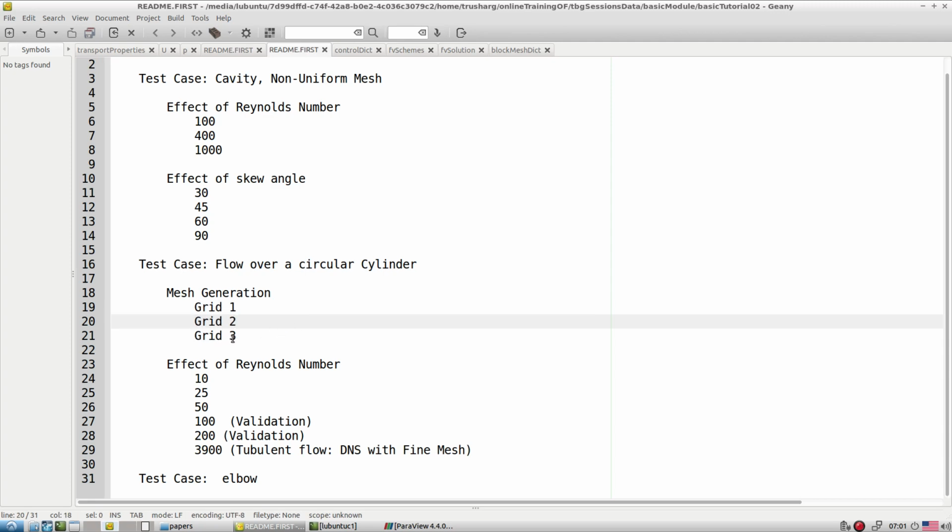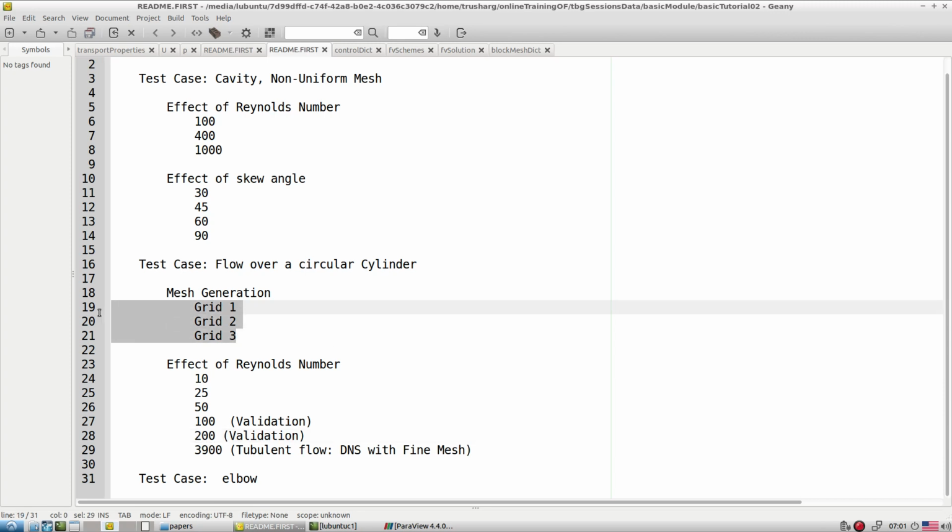With the grid independency, I suggest you check with a higher Re, 250 or 200, so that you get very good Strouhal number mapping. Do certain exercises with that, and then go towards very high Re. When you go toward very high Re, I suggest going with a very low delta t.